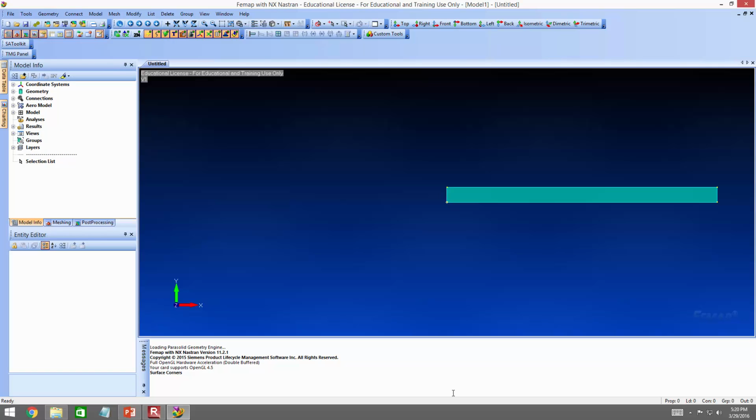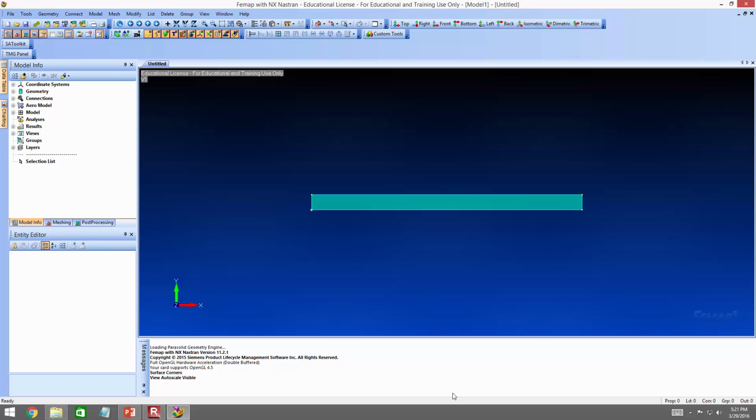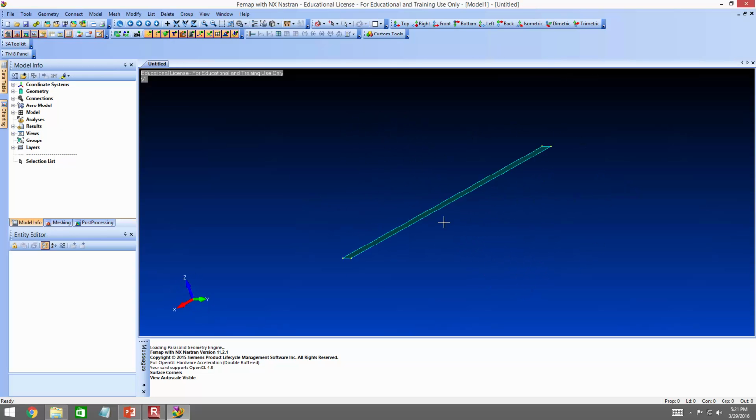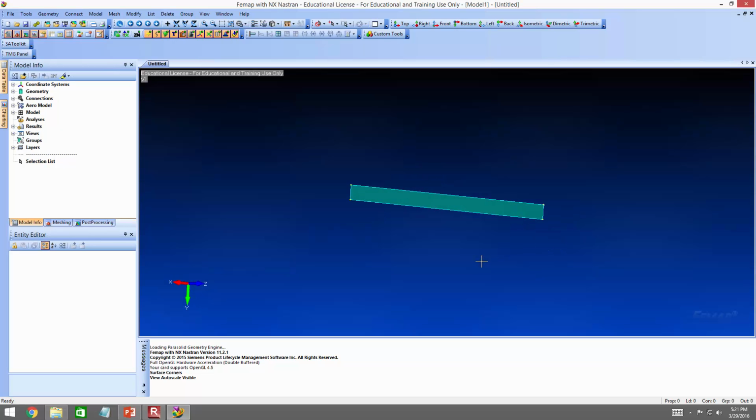Okay. Now, y'all know on Microsoft Word or Excel, you know how you hit Control A and that selects everything? If you hit Control A here, it centers your zoom, so you're centering the whole thing. So pretty straightforward. And if you want, you can take your mouse and click inside the screen and rotate it around a little bit. Now, this is not a three-dimensional beam because it has not been extruded yet, has it? Okay? So now I need to do that extrusion.